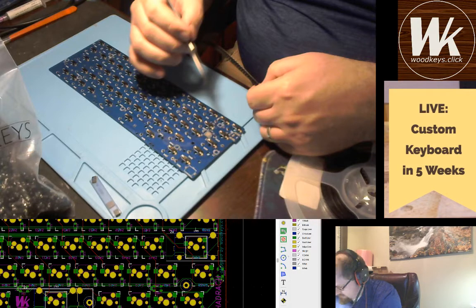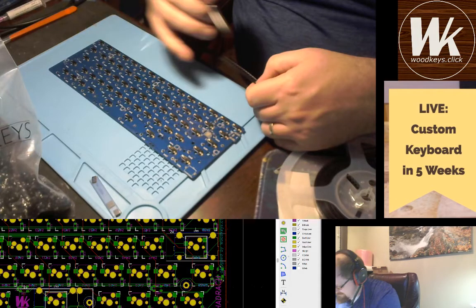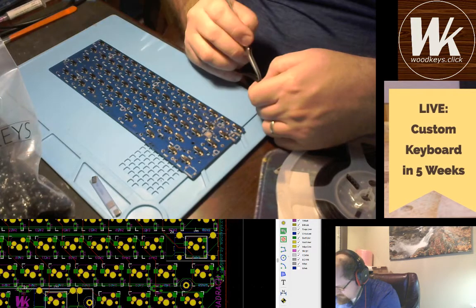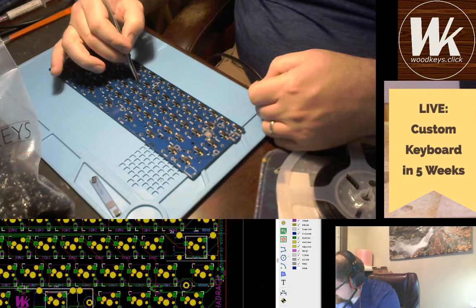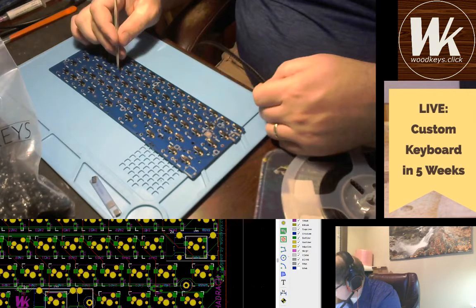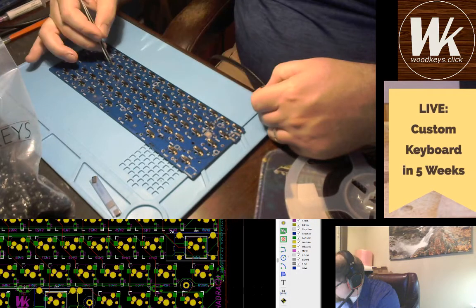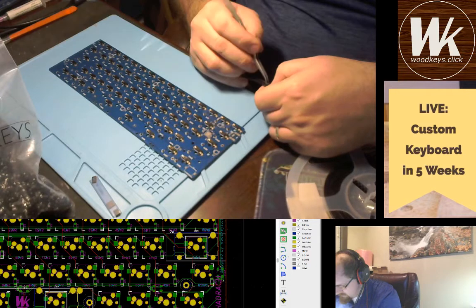It is a little bit slower on the pick and place machine. Not marginally. It has to spin them all around. Shouldn't take that much difference in time. But then when somebody's inspecting the board to make sure that every diode is facing the right direction, or if you're troubleshooting it, all that sort of stuff, consistency. It's all about consistency.